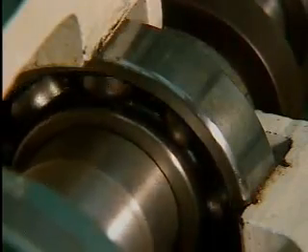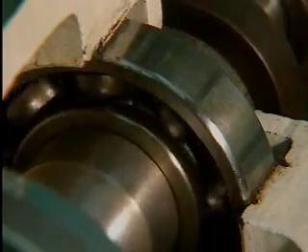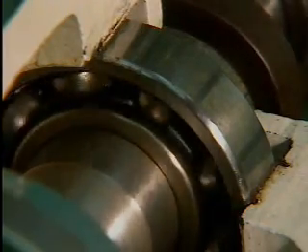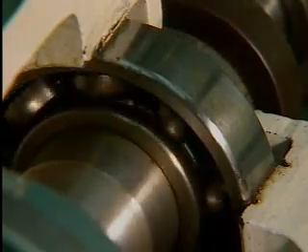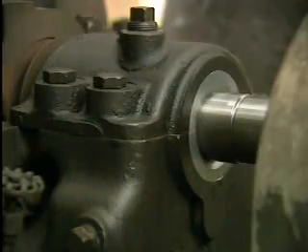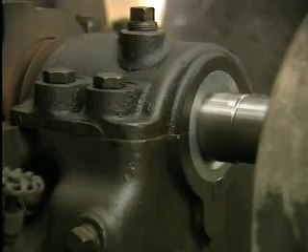Bearings that handle rolling friction have rolling elements, such as balls or rollers. These elements roll between rings to allow a moving part, usually a rotating shaft, to move easily. Bearings designed to handle sliding friction are built to allow a rotating shaft or other moving element to slide against the smooth surface of the bearing.